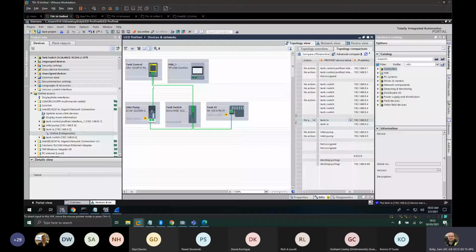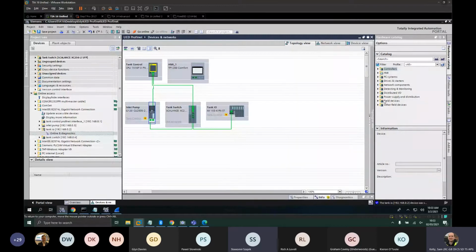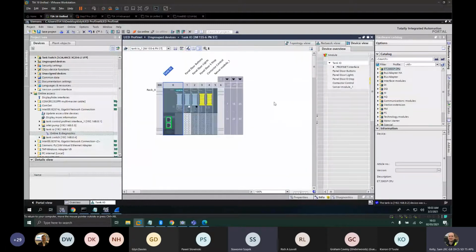Oh. This hardware detection, is it for all the Profinet devices or just Siemens right now? Which means if I connect SEW or, I don't know, a Phoenix Contact device. Sure, yeah. So the hardware detection in this case is just for Siemens devices. We do have to have the devices present in the hardware catalog. So say, for example, I didn't have safety installed and I was to do a hardware detection of the ET200SP here. It wouldn't bring in, I'm still showing my screen.